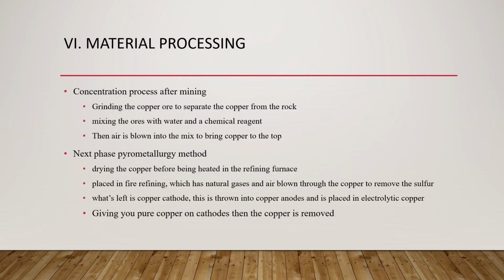The concentration process after mining. Grinding the copper ore to separate the copper from the rock. Mixing the ores with water and a chemical reagent. Then air is blown into that mix to bring the copper to the top, and then the copper is removed.